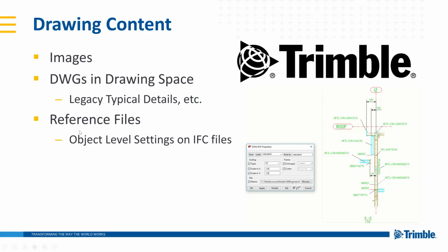And then you can also show all different kinds of reference files in your Tekla Structures drawings. Whether these be MEP or plant piping drawings or reference models, or an existing structure that's already been created and that you referenced in as an IFC file, or perhaps just an adjacent structure that you want to be shown because the property line is particularly close.